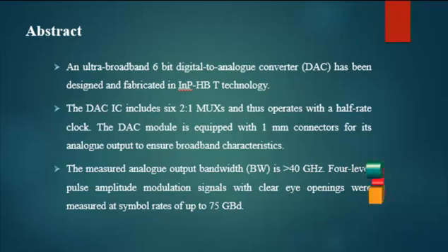4-level pulse amplitude modulation signals with clear eye opening were measured at a symbol rate of up to 75 GBd. This multiplexer digital to analog conversion module has the widest bandwidth of any previously reported digital to analog converters and is suitable for high symbol rate optical transmitters.